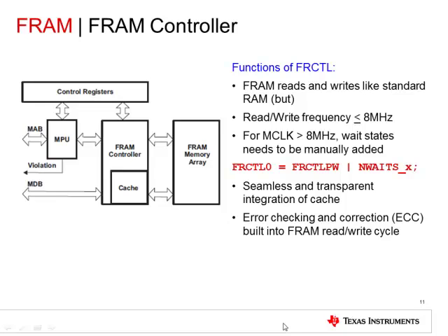The FRAM controller contains a cache with 2 cache sets. Each of these sets contains lines which are preloaded with 4 words during one access cycle. An intelligent logic selects one of the cache lines to preload FRAM data and preserves recently accessed data in the other set. If one of the 4 words stored in the cache lines is requested, also known as a cache hit, the FRAM is not accessed and the word is retrieved from the cache.